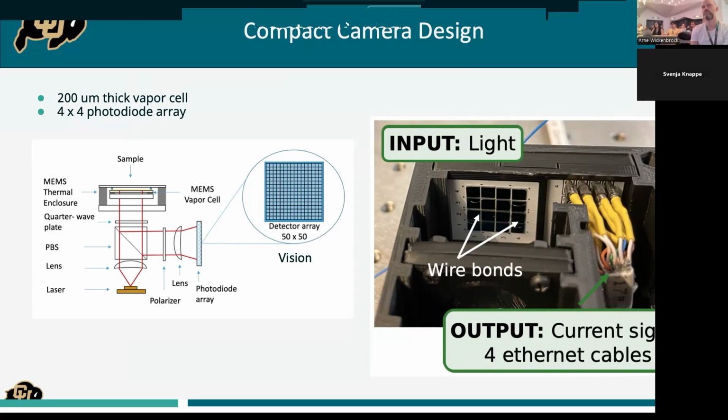If my gap is much bigger than the size of my pixel, then we're in the far field, and I don't think this makes any sense because everything will be smeared out. Maybe you can engineer it smaller, but I really don't think it makes sense to use atoms anymore. Well, it's already cool that you can go down to 50 micrometer width and still get decent sensitivity. Width. Yeah, width, sorry. The thickness is still 200. What's thickness again? 200. Yeah. Okay. And again, we can change the thickness too, but it's much harder to change because every time I'm doing a new wafer, while it's really easy to change in lithography the lateral directions.